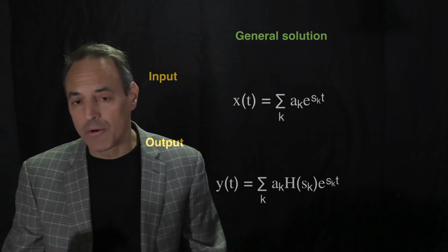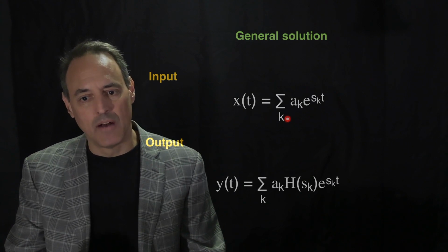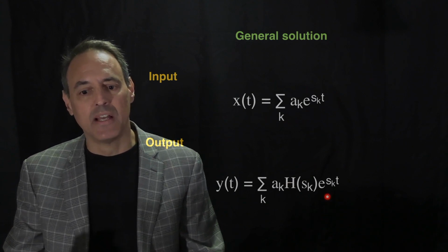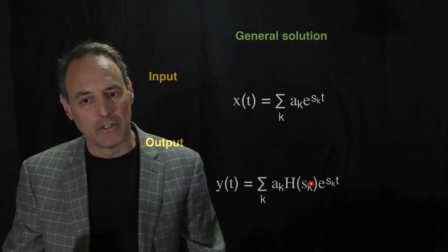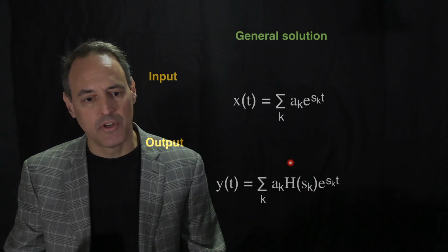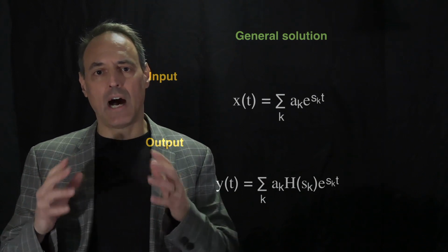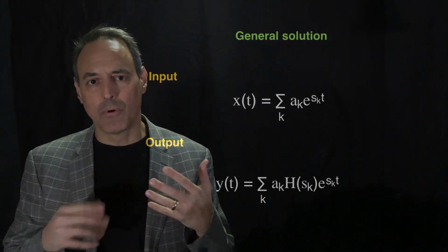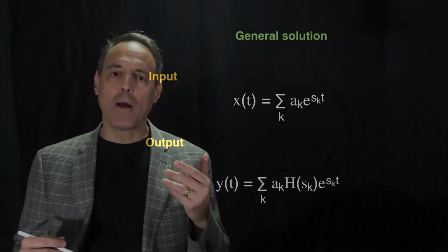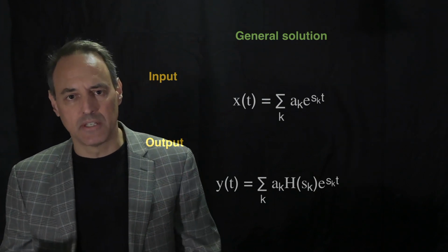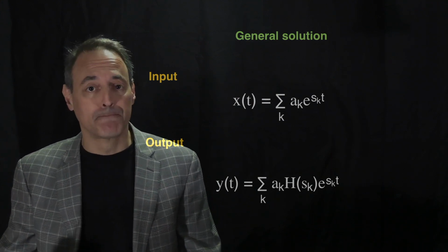Okay, so more generally, if I had a signal that was made up of a sum of exponentials, then the output is the sum of exponentials, again, multiplied by this eigenvalue for each of the exponentials. Okay, so there's that input-output relationship. So this is really nice. The fact that these are eigenfunctions of the LTI system allows us a very simple construction of the input-output relationships. And so this is why we want to use exponentials in LTI systems, or Fourier representations, which again are just our exponentials.